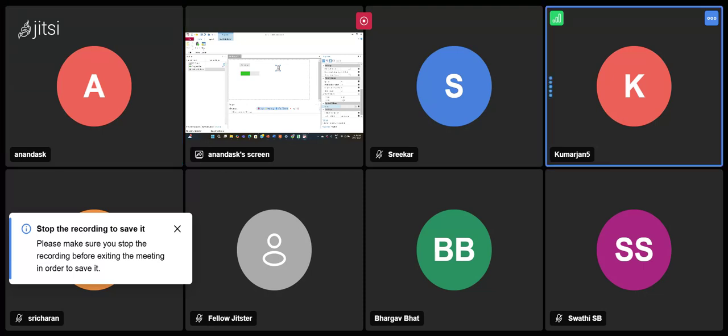And also, we can add the automation part, right? When you are trying to automate some of the tools, you can use this panel design, put the button over there, and try to automate that. Call those signals through CAPL scripting, and it will go automatically and sequentially. So, we generate a .can file from the CAPL script, load it in one particular environment of CANoe, and then you can use this panel design to activate those .can files.